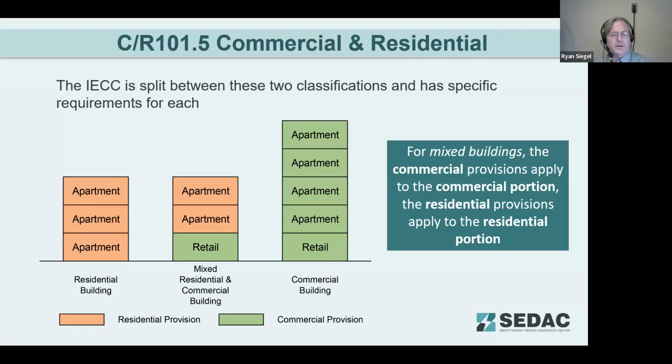Now, residential construction as defined here in the state of Illinois is residential buildings, single and two family dwellings, along with multi-dwelling units where occupants reside predominantly on a permanent basis, of 3 stories or less. So as we see on the left, that is a fully residential building. On the right, because we are over 3 stories, in particular in the City of Chicago you get 1 extra story for 4. Since we're even above 4 stories, regardless of where this is in the state, that is a commercial building on the right, because we are above that 3 to 4 stories.